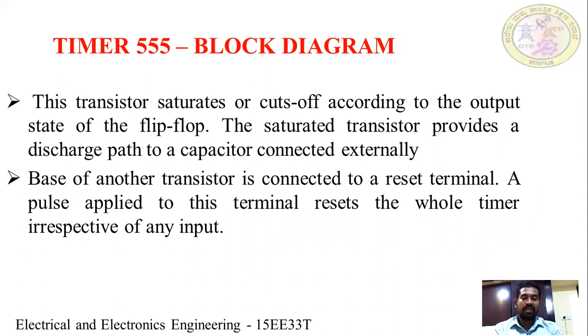According to the flip-flop output state, the transistor reaches the cutoff region. So that saturated transistor provides a discharge path to a capacitor which is connected externally.